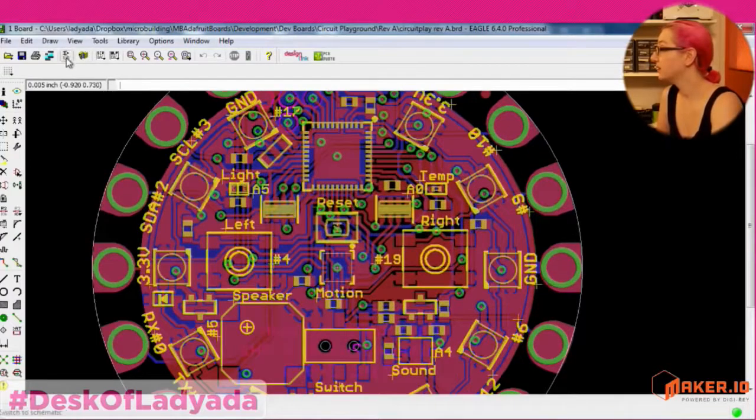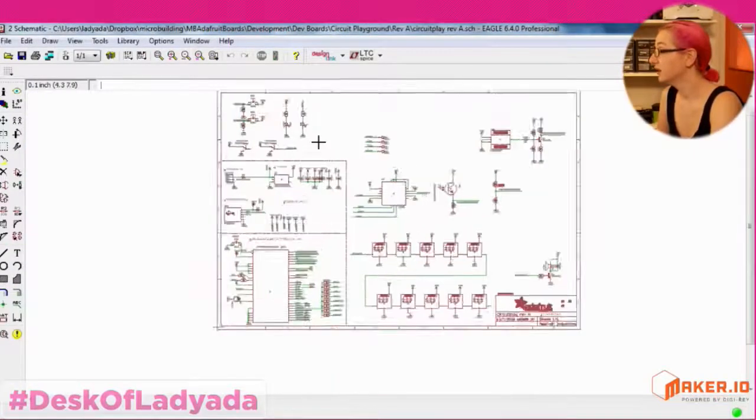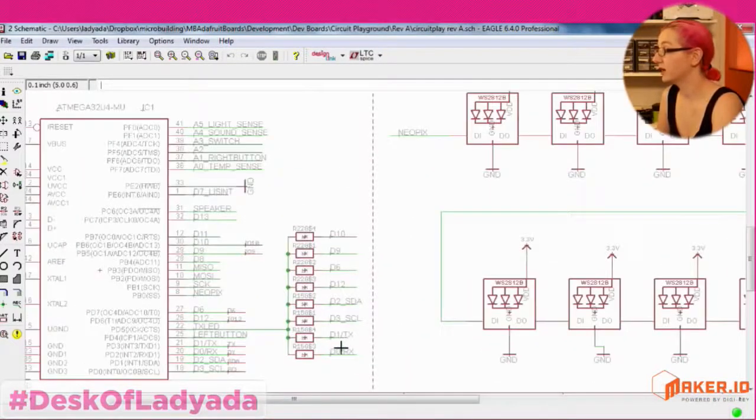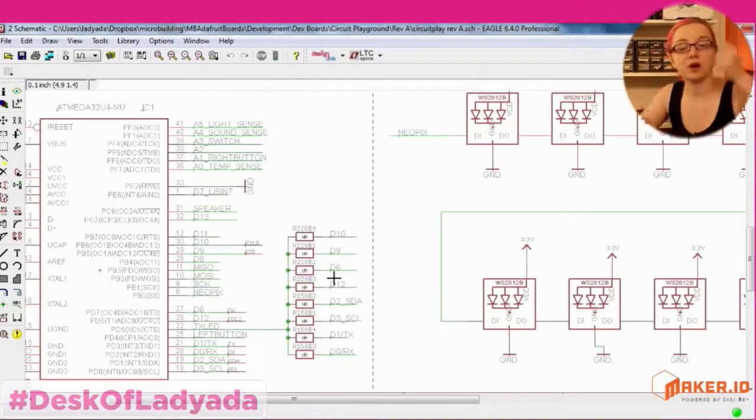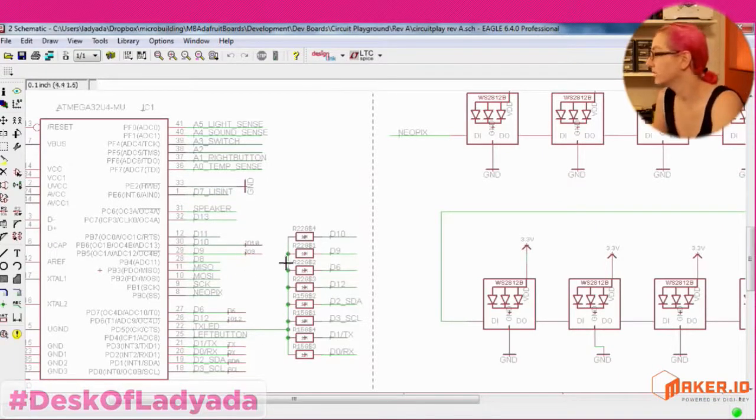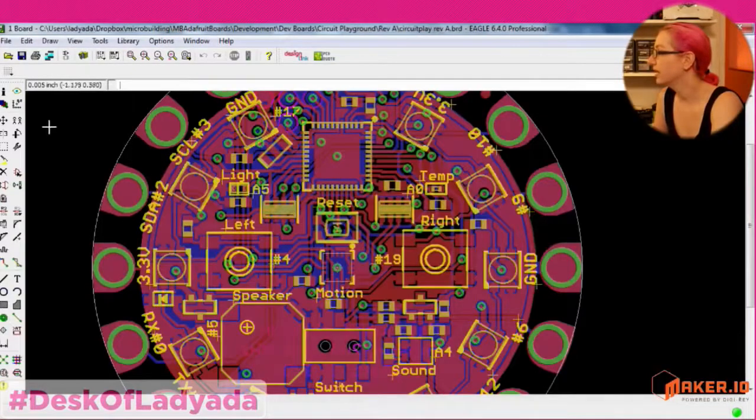Another thing I did when I designed this is I wanted to have capacitive touch on all the pads. You need a pin with a 1 megaohm resistor between the pin and the pad, and you have to toggle between 2 pins. So I recycled that TX LED pin that was used for the transmission LED, and I recycled it into using it to do capacitive touch. And so I have these.